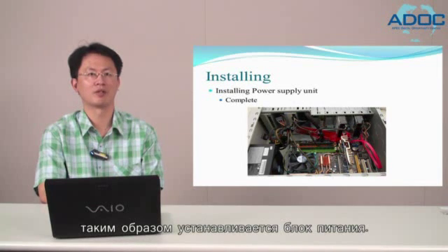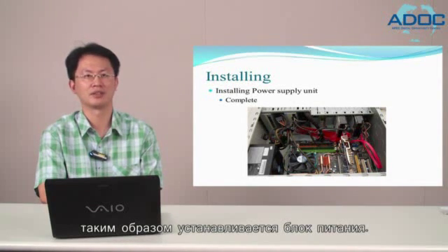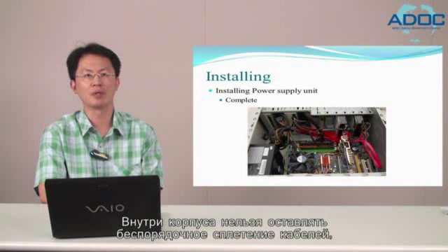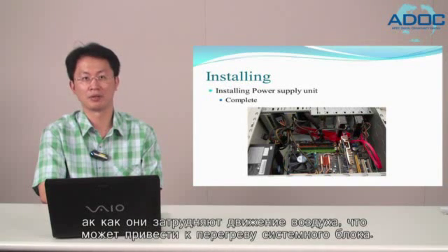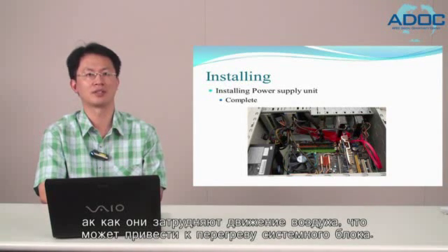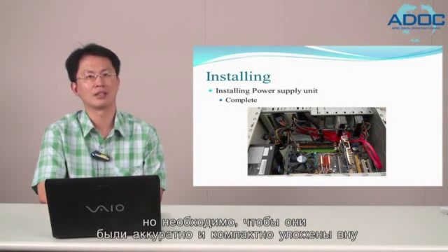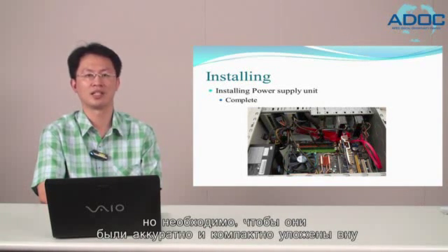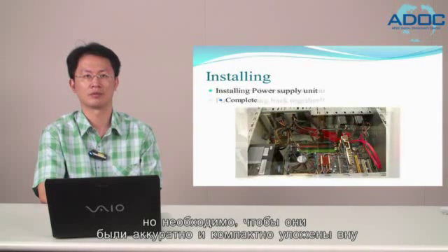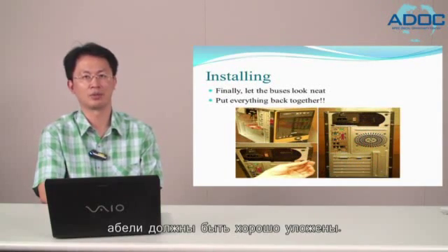And this is the completion of the power supply installation. Leaving cables rumpled or overrun inside a case inhibits airflow and can lead to a system running harder than it has to. It's always worth taking a little time to wrap, tuck, and tie up cables for a neat finish. So one last thing to do, keep the cables organized.